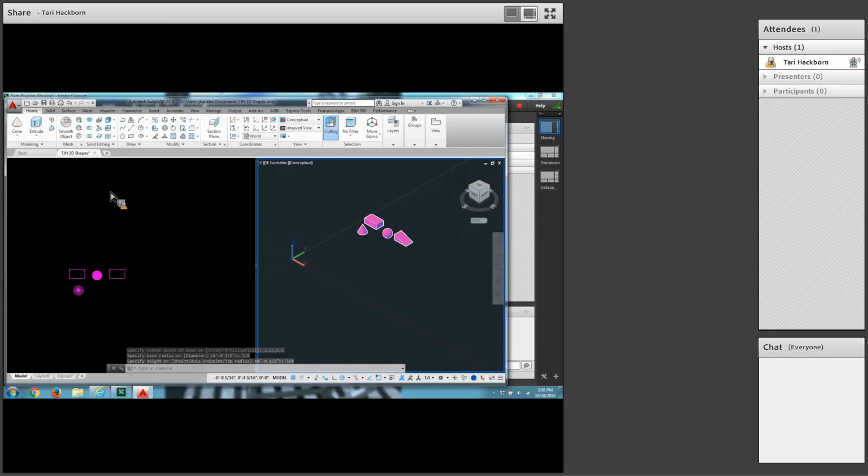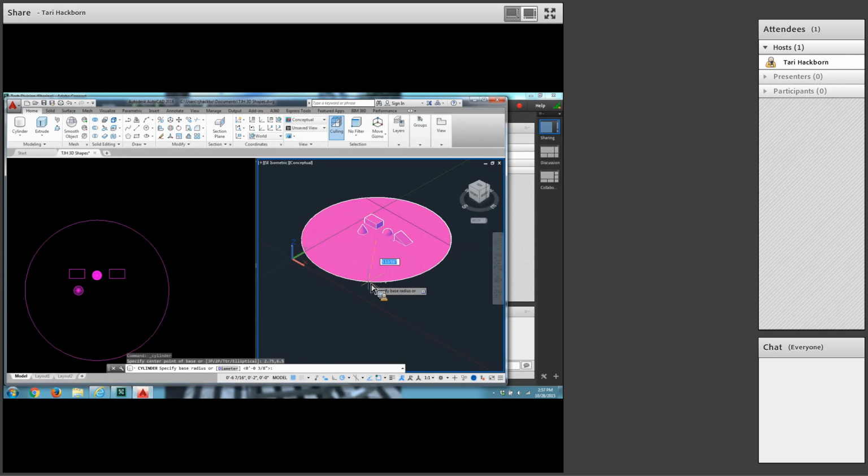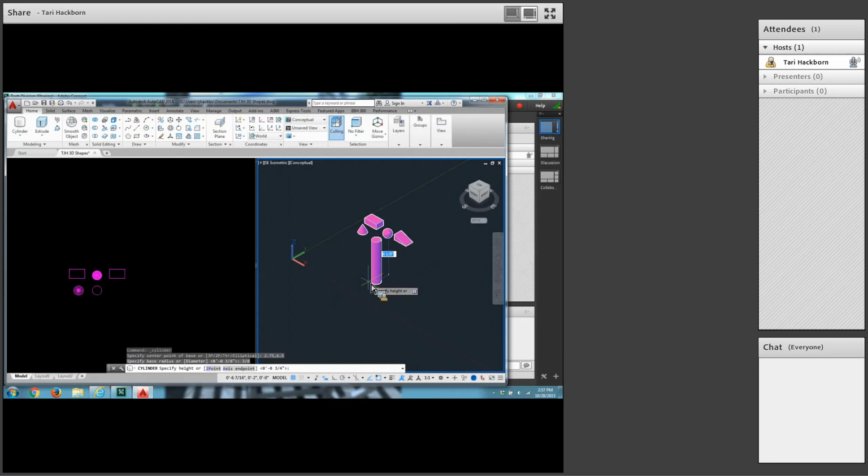Cylinder. Okay, let's turn to page 52. And grab the cylinder right here. The cylinder begins at 2 3/4, 6.5. Okay, so 2.75, 6.5, enter. It also has a radius of 3/8, and enter. And make sure I'm pulling upward, a height of a 1/2 inch.